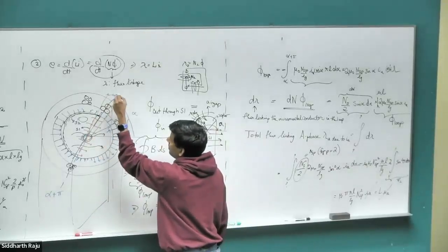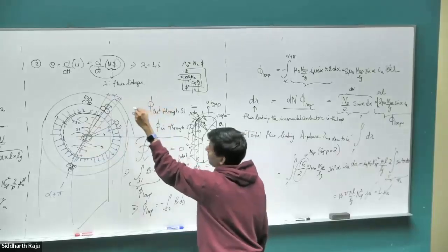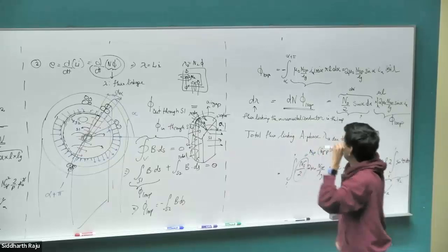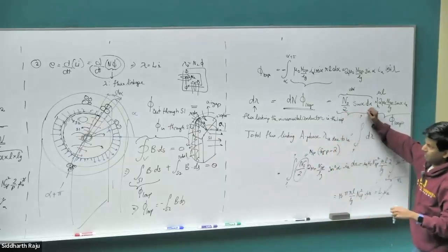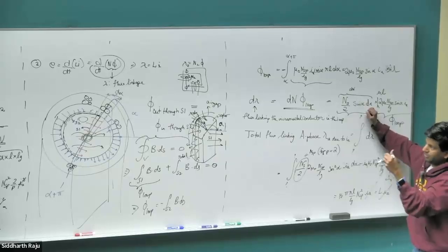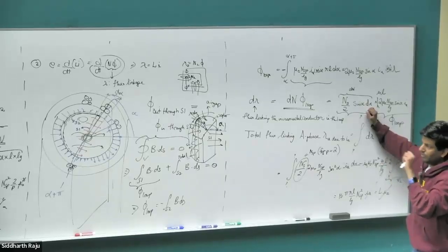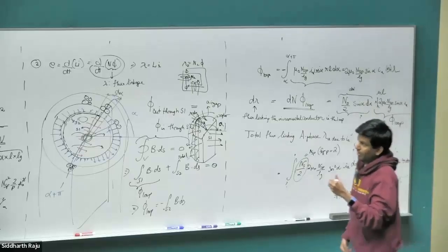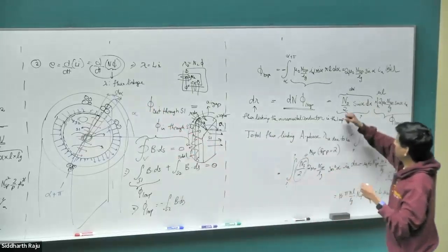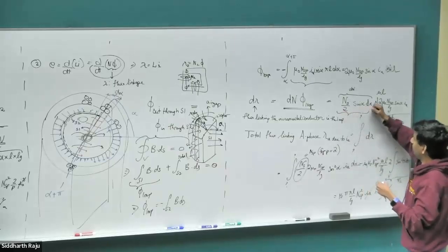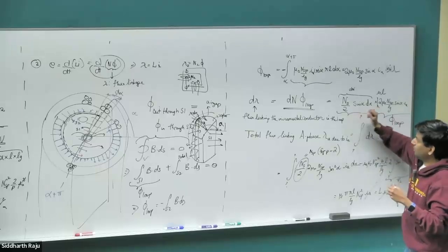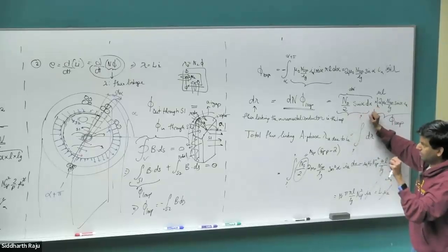So this angle is again some alpha. So this spread is some d alpha. I take the conductor density, multiply by d alpha, and I'll get the total number of conductors here. If I do the integration from some angle to the other angle, I'll get the total number of conductors in the slot. If the d alpha is small enough, instead of doing the integration, I can just multiply the term. Because assuming that this function does not vary over the incremental length I've chosen, I can just make it a multiplication instead of an integration.